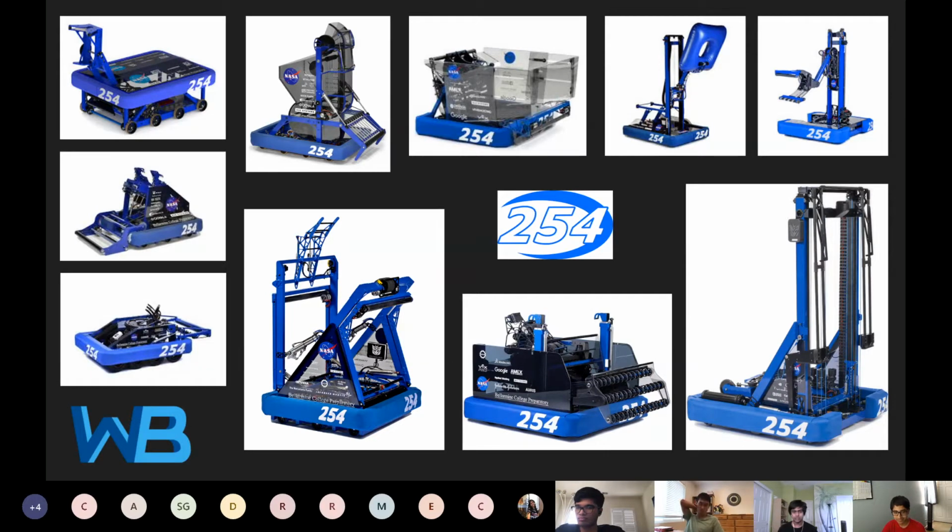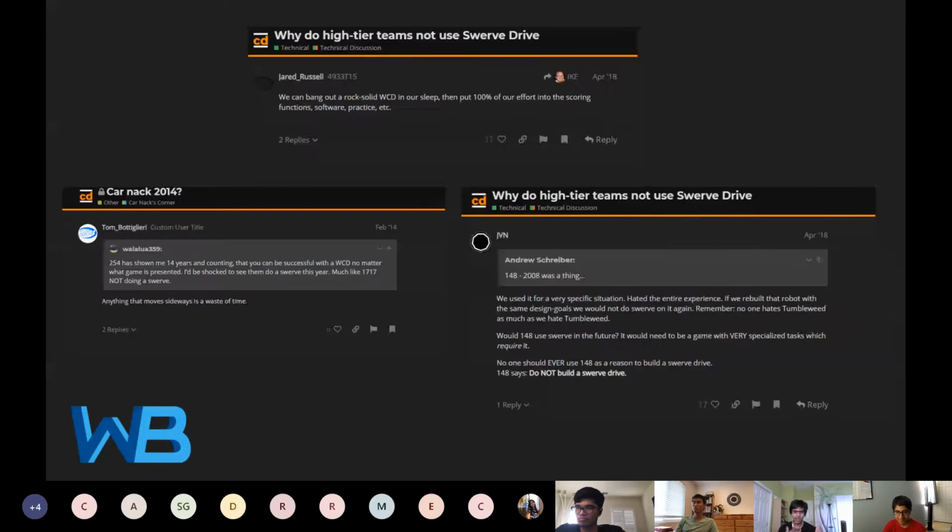Choosing to build a different type of drivetrain, specifically the one referred to here, a Swerve Drive, where you can move omnidirectionally, in any direction around you, and spin, is less valuable, or the added value is not worth the cost of time required. That's the idea here, which is what Sadesh covered: as much functionality for as little complexity is what you want to aim for in design generally.